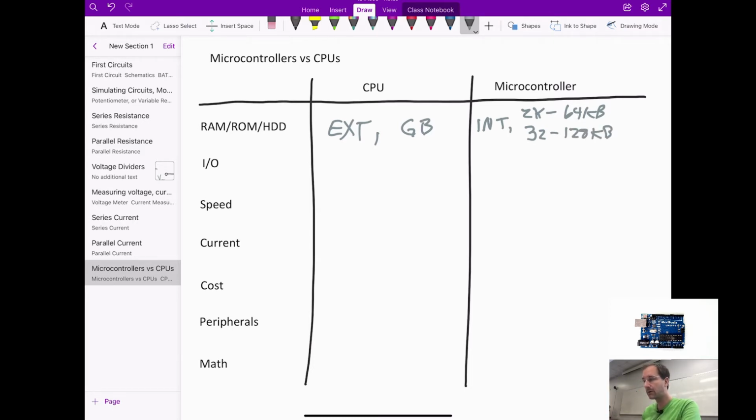So it's very, very much less, right? Can you imagine, as you soon won't have to imagine, because you'll be doing it, writing a program that only has 2K of memory total for the entire execution. And so if you make an array that has 1,000 elements in it, and those 1,000 elements use 2 bytes each, say for an integer, low resolution integer by desktop standards, you've used your entire program memory, you can store nothing more, and your program will just go tilt. So it's much, much less program space, and it really forces you to think very differently about efficiency.